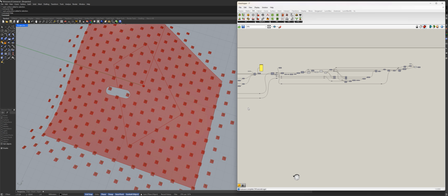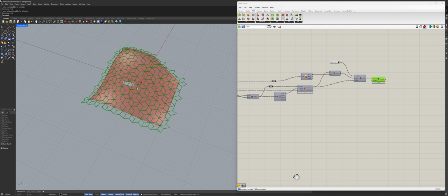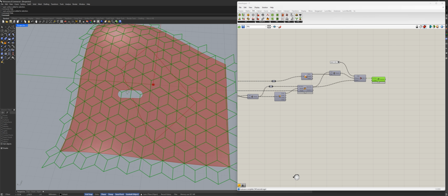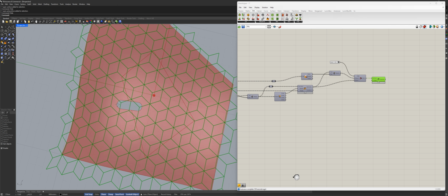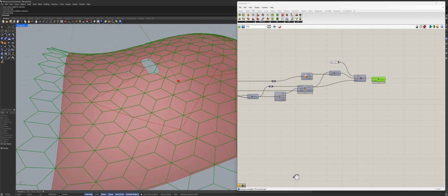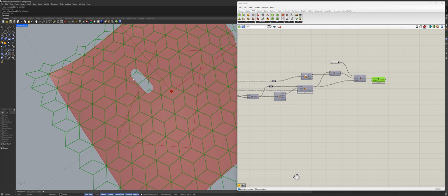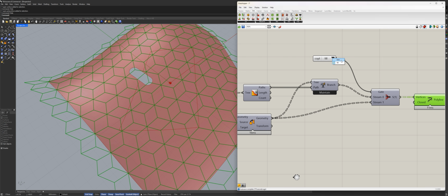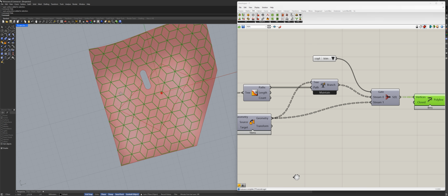All right. Did I mention everything for this or not? What next should I mention? Oh yeah, you're going to see there is a hole here, right? But you're going to see it's actually not a problem for the hexagons at all. It just passes through and projects everything it needs on the proper positions, right? What if you want to have the hole? What if you don't want your elements to be inside? Well, they actually will not be, because we will eventually bool this out. It doesn't matter if there is something in here, because we have on top of that a trimming operation, and you're going to see it will not even go here.